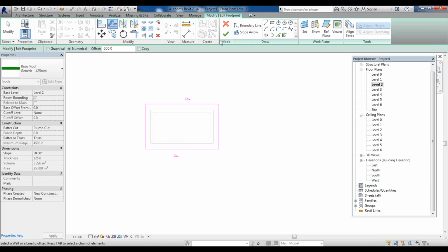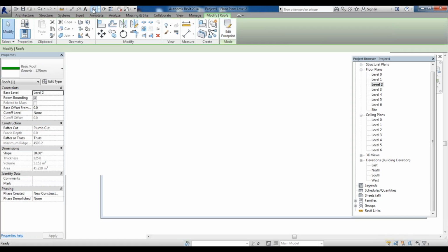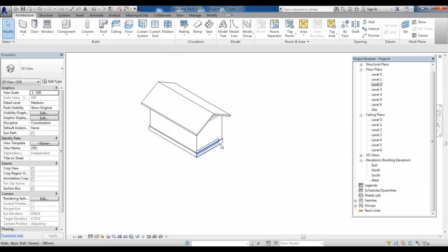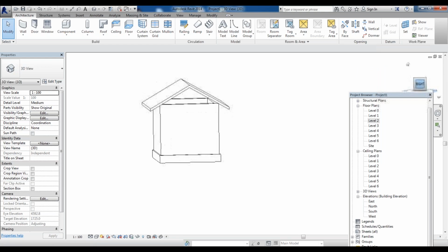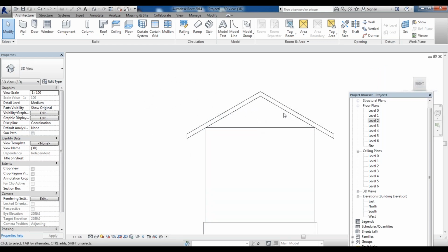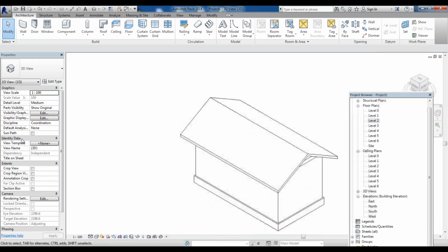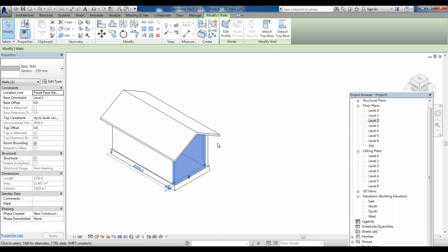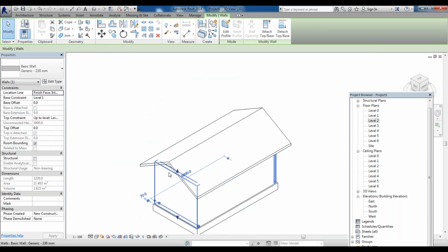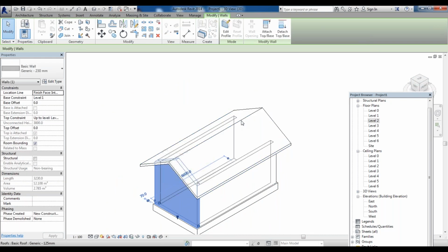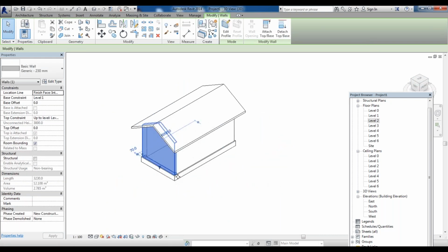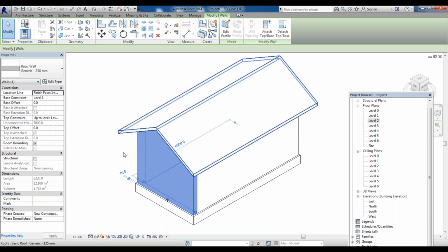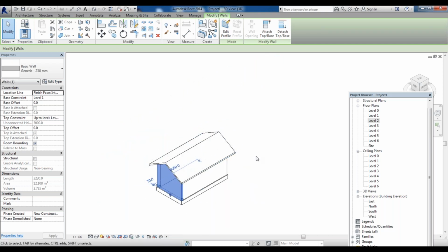and just clicked it. So it created beautiful roof around the house. You will also notice that in 3D, if I click right, you'll see there is a gap from the wall to the roof, which we are supposed to correct. How do we do that? So you select the wall and say attach top base and click the roof. That's all. So you go to this corner, select this, attach top base and click here. Okay, that is done. So you have a covered area over here.